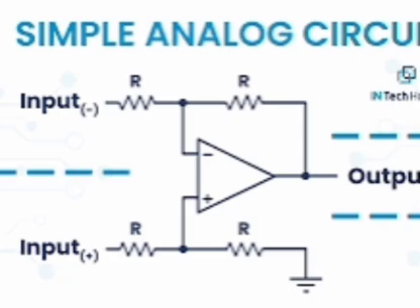TUF percentage of half wave rectifier equals 28.7 into RL by Rs plus RL plus Rf. TUF percentage of center tap based full wave rectifier: 69.3 into RL by RL plus Rs by 2 plus Rf. TUF percentage of bridge circuit based full wave rectifier is 81.2 into RL by 2 Rf plus RL plus Rs. Output frequency of half wave rectifier: F. Center tap based full wave rectifier: 2F. Bridge circuit based full wave rectifier: 2F.